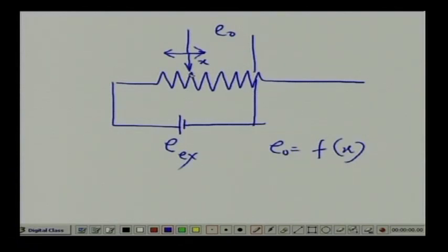Regarding resolution, in a potentiometer, even though I am showing here that it is getting contact with only one turn, the potentiometer actually looks like this, is it not? So, this wiper will always contact more than one or two windings.